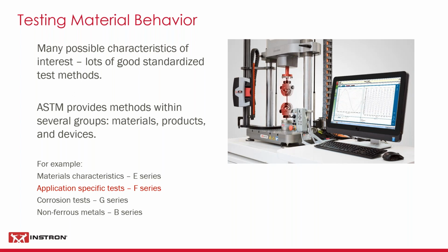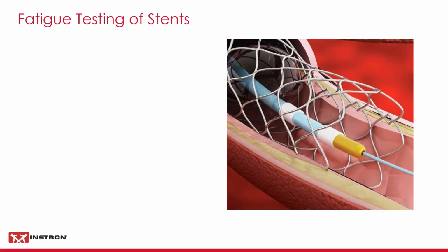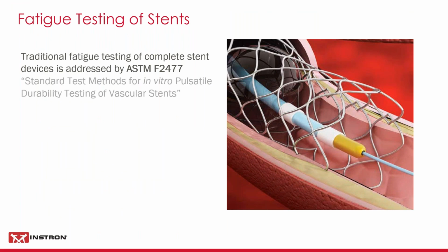All this sort of stuff, I'm always happy to have a conversation about, and my colleagues in sales support can equally help you. So let's get on to the thrust of what we were aiming for today, about fatigue testing of stents. For a very long time, the test has been laid out in this F2477 standard, and it's pulsatile durability testing.